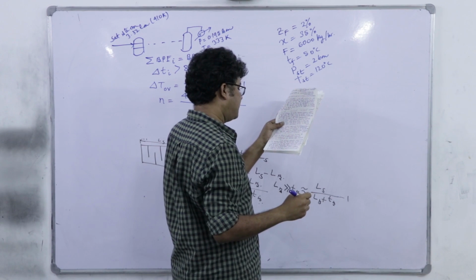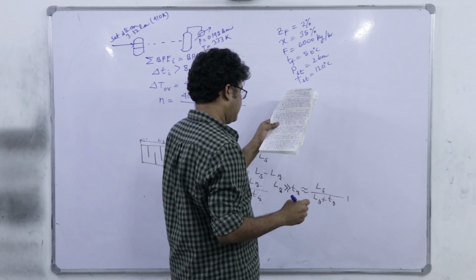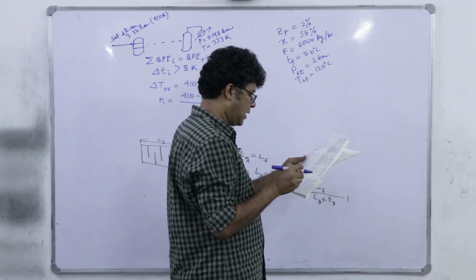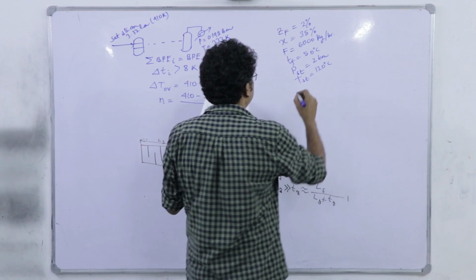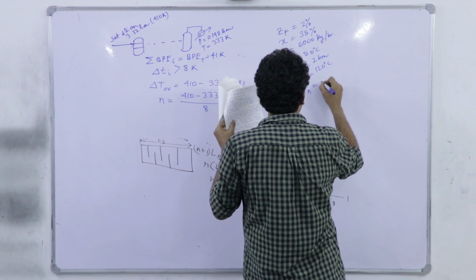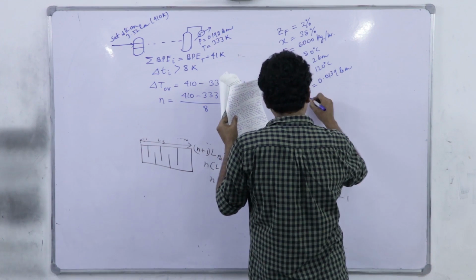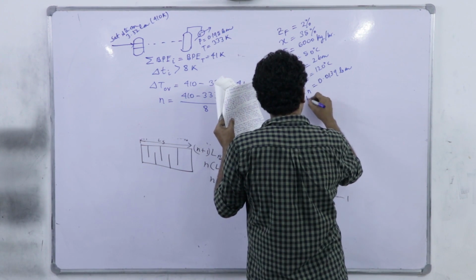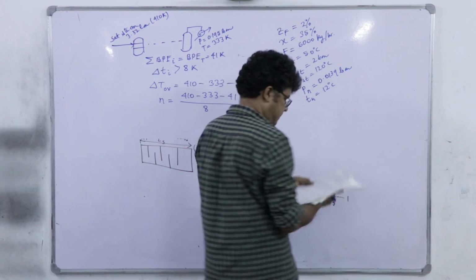It is supplied to the first effect while the pressure of 0.019139 bar is maintained in the last effect. So Pn in the last effect is 0.019139 bar. Corresponding temperature Tn is 12 degrees.